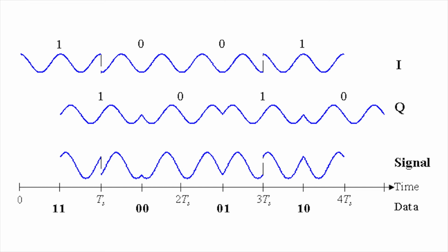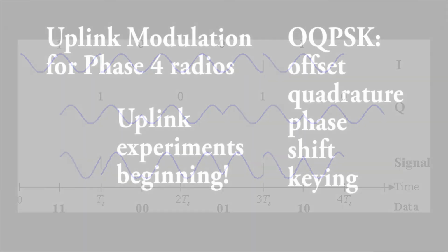This is good. In order to create this, you begin with a QPSK signal, where you take 2 data bits at a time. These 2 binary data bits make 4 distinct values. Each of these values are mapped onto 4 transmit phase shifts. For offset QPSK, the odd and even bits coming into the modulator have a timing offset of 1 bit period, hence the name. That means the in-phase and quadrature signals, the I and the Q, never change at the same time. The power spectral density of QPSK and offset QPSK is the same. The shift in time doesn't affect that.